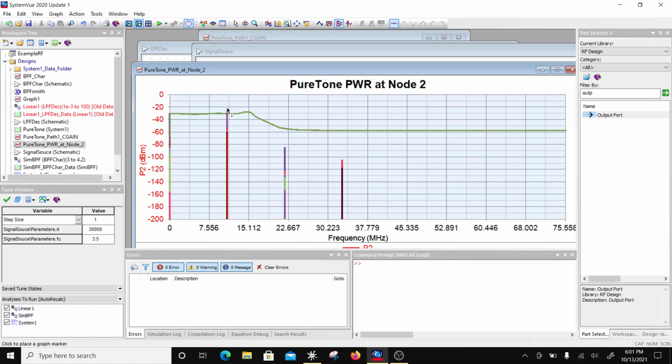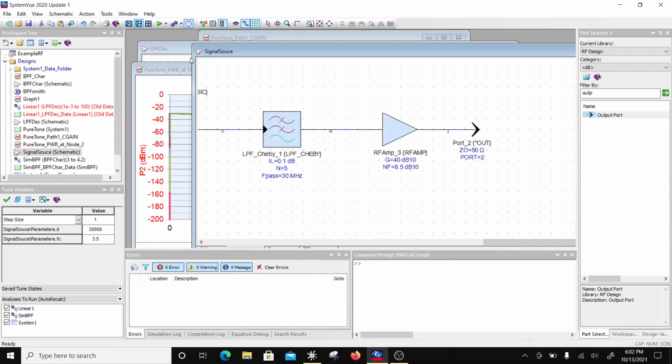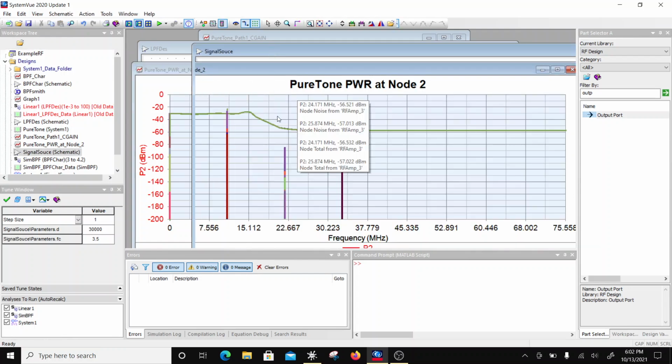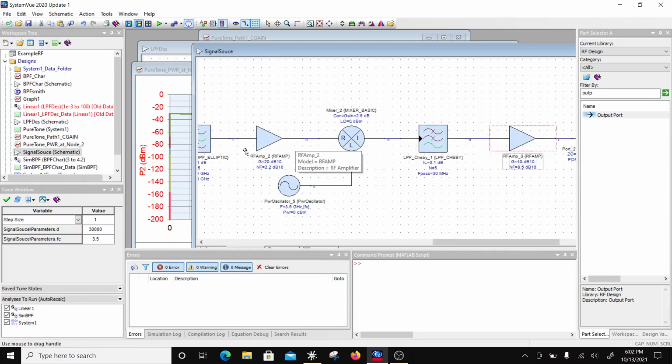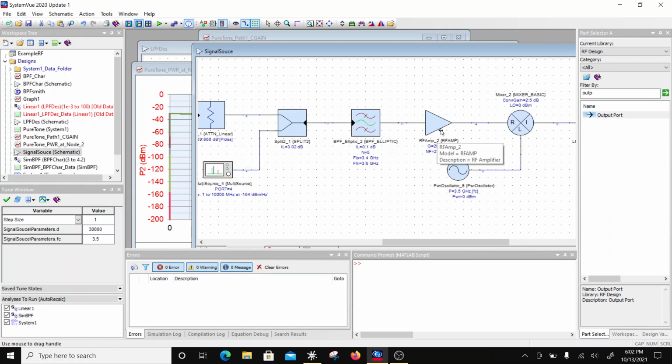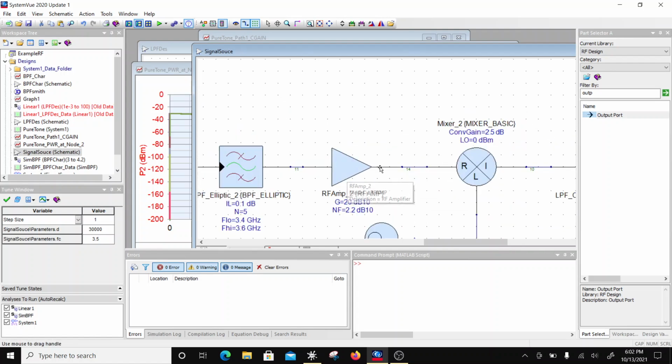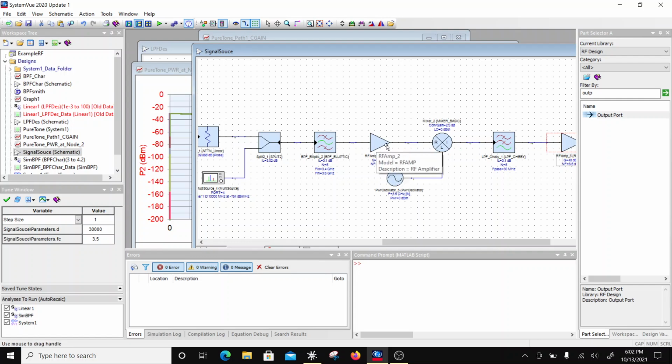And you have to look at the highest distance and the shortest distance to see what dynamic range you should be operating in. And this would result in maybe a variable gain IF stage. So the IF stage which I have added can be a variable gain. And again, if you are looking at the SFDR of this entire receiver, then a portion of this gain may come from a variable gain LNA, right? So that will increase the SFDR.